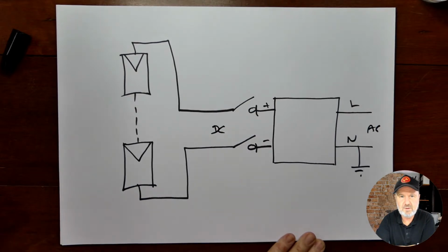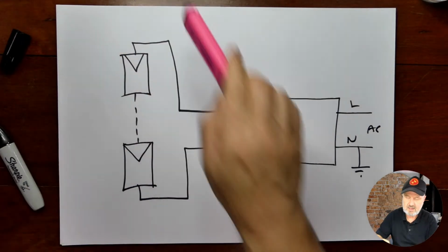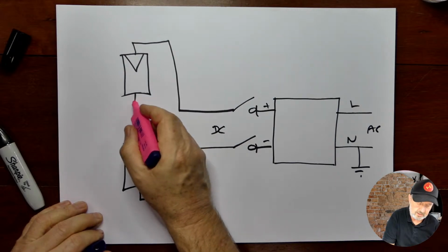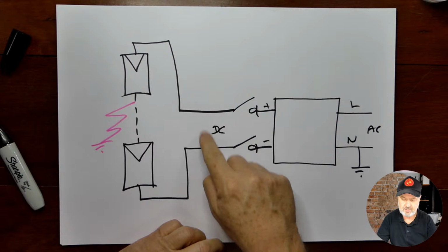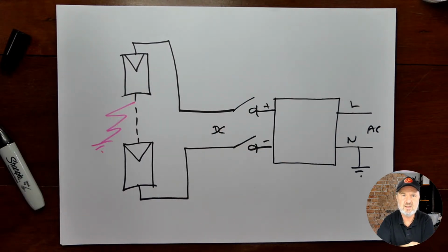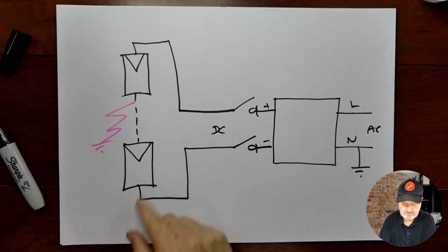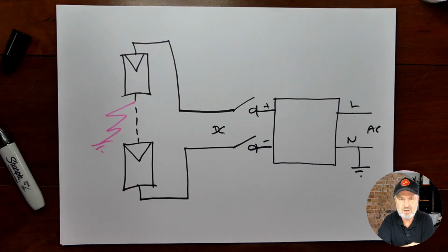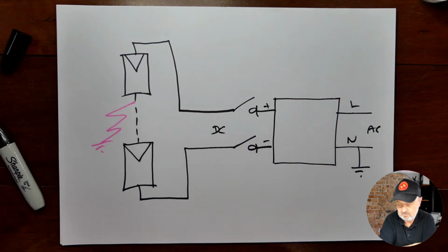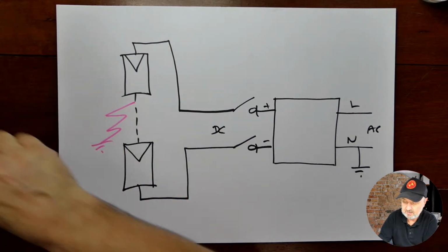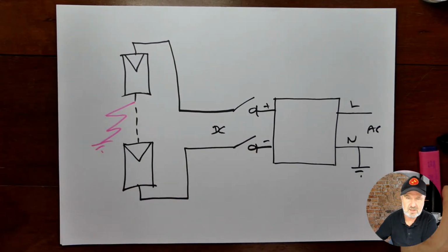And therefore, any faults on the DC side had no impact. So if I draw a fault on here to earth, there is no reference to earth on the positive or negative conductor in this diagram. And therefore, that fault actually does nothing. It doesn't actually create a fault current. It's just referencing one of the poles of the array to earth. It may significantly impact the inverter's performance, or it may not. The system's floating. It's unlikely to impact unless there's some earth fault detection system.